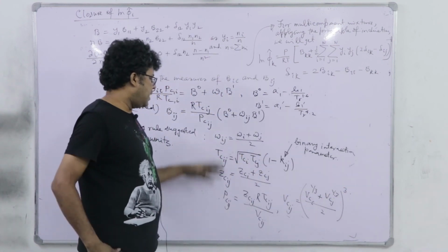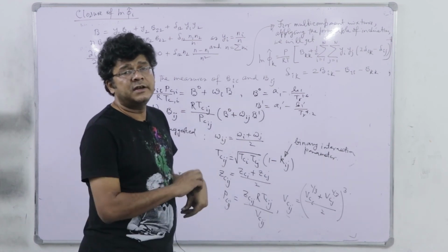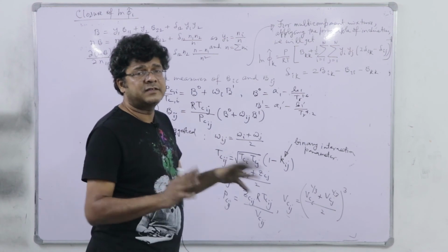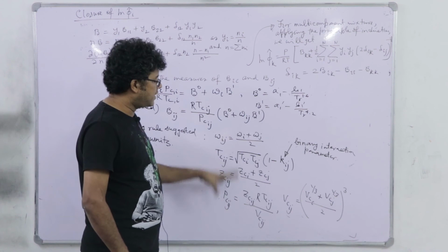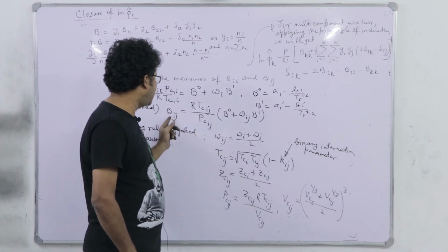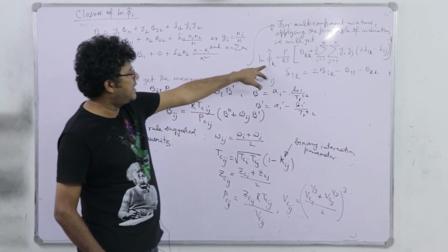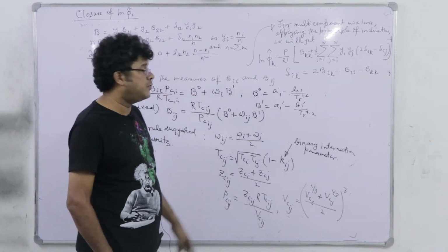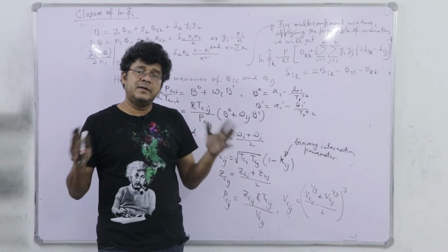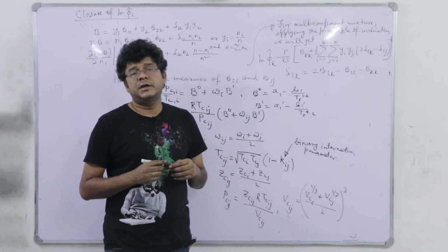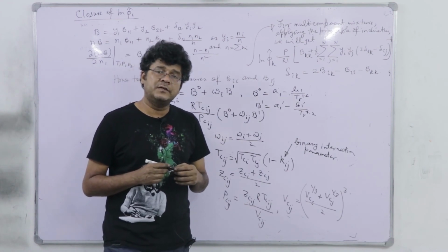So, you see that these are the mixing rules suggested. Mixing rules are empirical, but they give a very good estimate of ln phi i cap, because based on the accuracy of this estimation of Bij, we will have the accuracy of ln phi k cap, or phi 1 cap, phi 2 cap in case of a binary system. So, this is the closure and the demonstrative example for the calculation of component species fugacity coefficient.